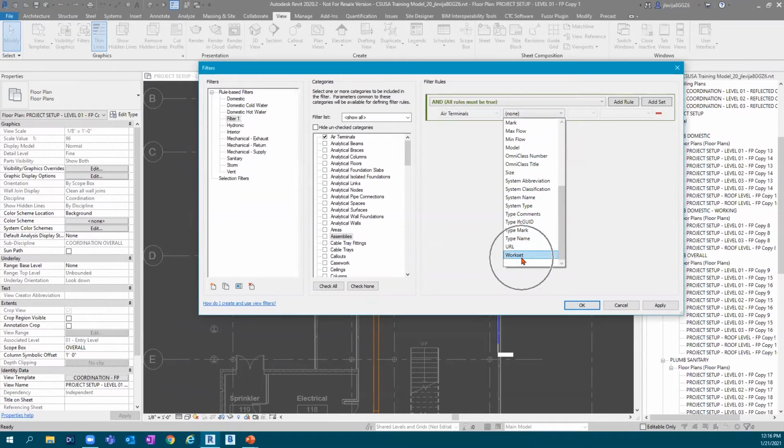Okay, so you can set something based upon worksets. Say you've got a workset designed for, and I've done this once or twice, new construction, and then a secondary workset designed for an add option, per se. You can actually adjust your filter to turn that on or turn that off according to that specific workset that's on or off within your view.